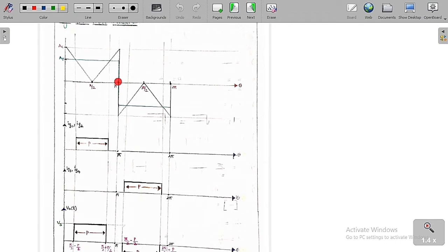Only this triangular pulse is going to give you the pulse width in 0 to pi, but it is not going to change the frequency. So if you want to change the frequency, then change the frequency of this reference signal. If you change the frequency of this reference signal, we are going to change the frequency of the output signal. Simply, the frequency of the output signal is equal to the frequency of the reference signal.